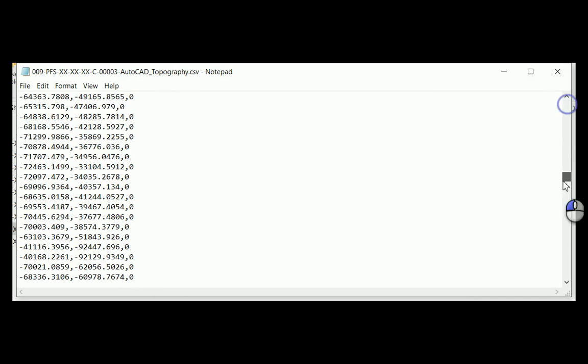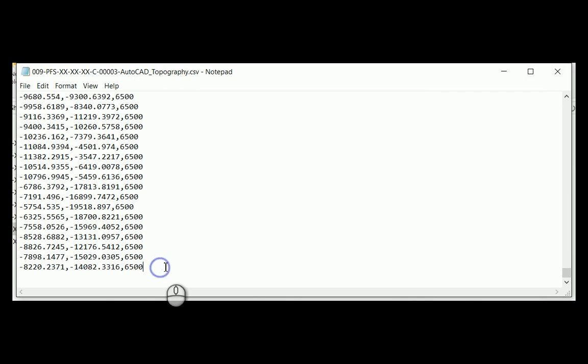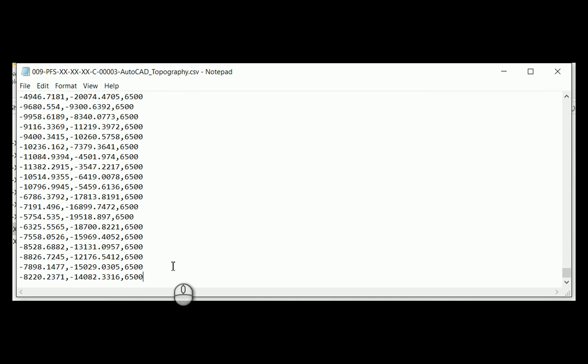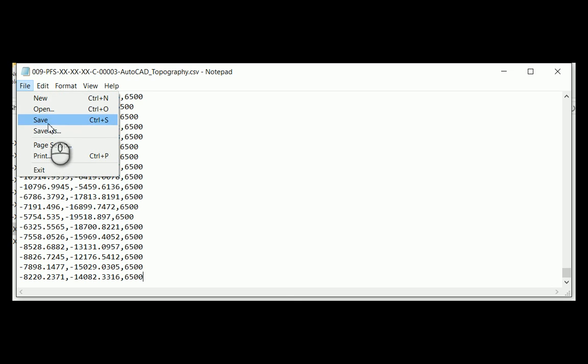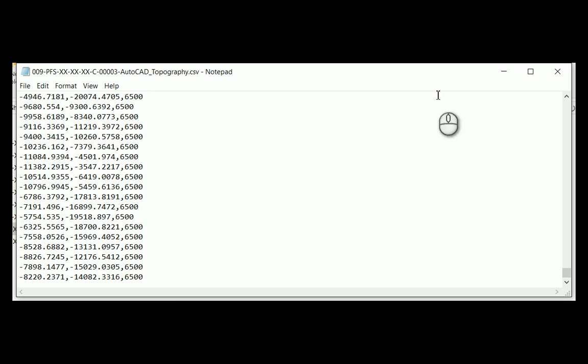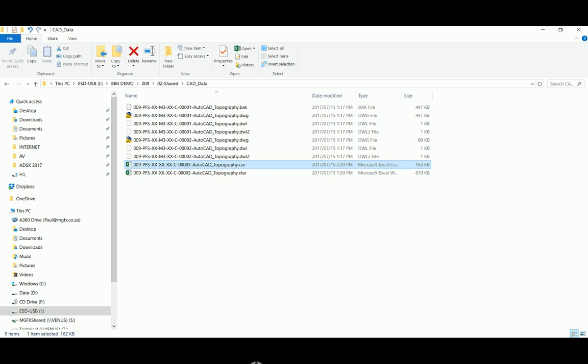And in addition, right towards the end of the file, there's a carriage return line feed that needs to be deleted as well. Revit interprets that as enter or new. If that carriage return line feed or the enter is in the file, Revit will reject this file, so I can save that now. Save and close.